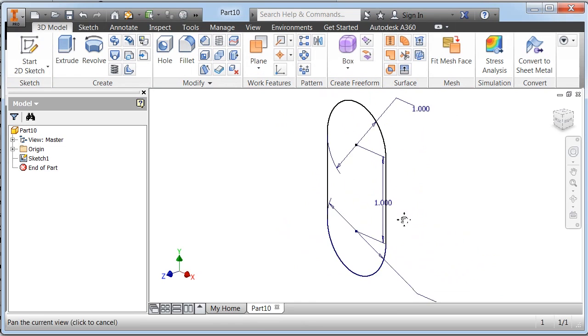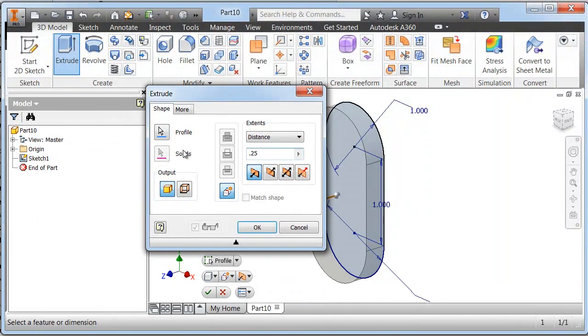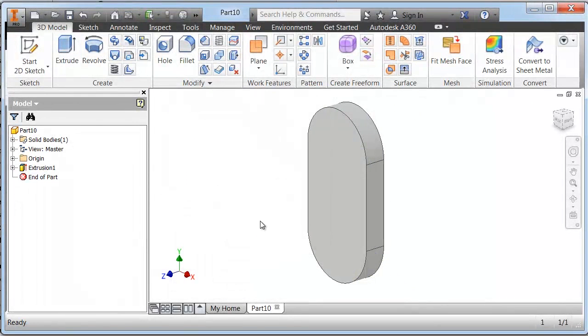We'll scroll it out. We'll hit extrude, 0.25. Left click on OK, and we'll put a 1/2 inch pin up here, and then a 1/2 inch pin on the opposite side. So we'll move the cursor to this left side. When it becomes highlighted, we'll right click once.